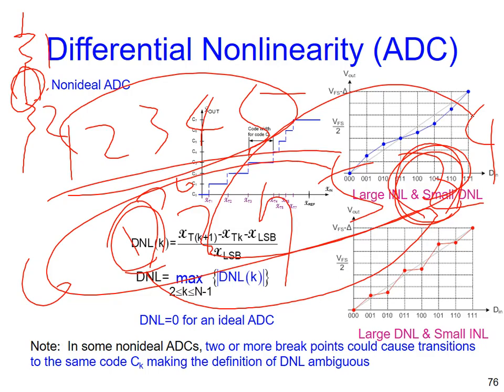And you need to pay attention not only to the complexity of the layout, but also the parasitics. That is perfect in idea, but for real implementation, sorry for that, it is very difficult to implement, and you will get a lot of parasitics. Maybe sometimes the parasitics will kill your performance. All right? So nothing is free, pay for it.